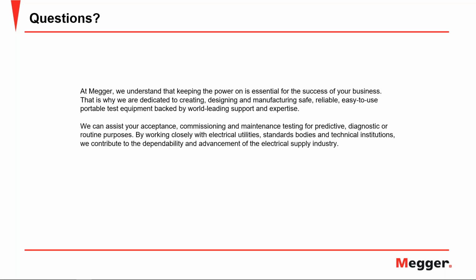Because of that, when you're doing commissioning testing, or when there is an outage at a data center or hospital, it is typical for technicians and engineers to perform primary injection tests. There are some other tests that go along with this, like insulation resistance and low resistance measurement. Those are some of the other tests you would do on low voltage circuit breakers. But coming back to primary injection, it's a very standard test recommended during commissioning and maintenance, just because of the value that it provides.